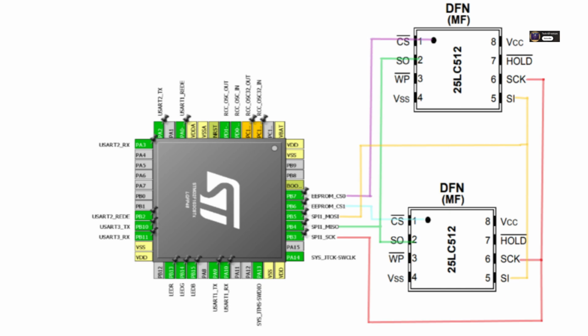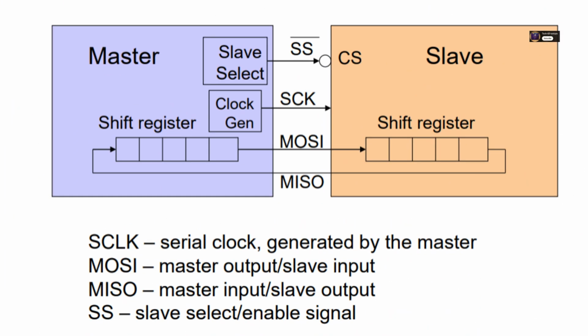Okay, those seem like big ones related to the commands and timing. What about hardware issues? Absolutely. Signal integrity issues, especially at higher speeds. Long traces, noise, reflections, they can garble data. Keep traces short, use ground planes, maybe add those series resistors. Chip select glitches, especially during boot up. If CS floats low briefly, the chip might get activated unintentionally. That pull-up resistor on CS helps prevent this. Also, ensure your GPIO is initialized high before enabling the SPI peripheral.